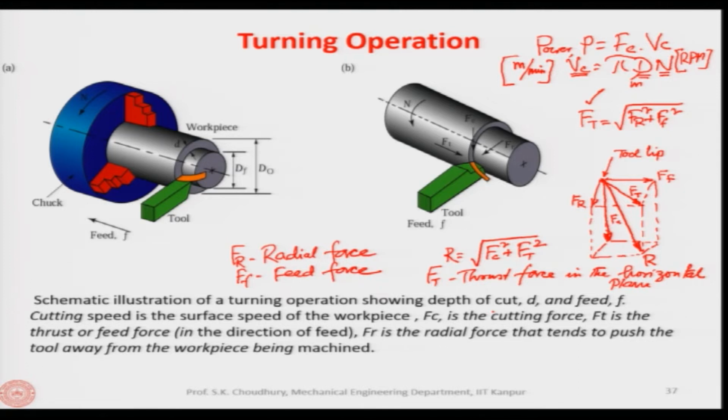So, those discussions that we had in our last class, that we should judiciously select the angles, these cutting parameters like the rake angle of the tool, are for that purpose, so that the machining operation can be performed in an optimum way, with the shape, size, finish, accuracy obtained at minimum cost.